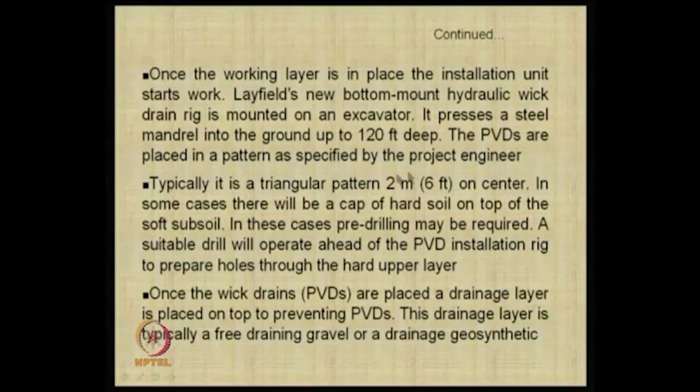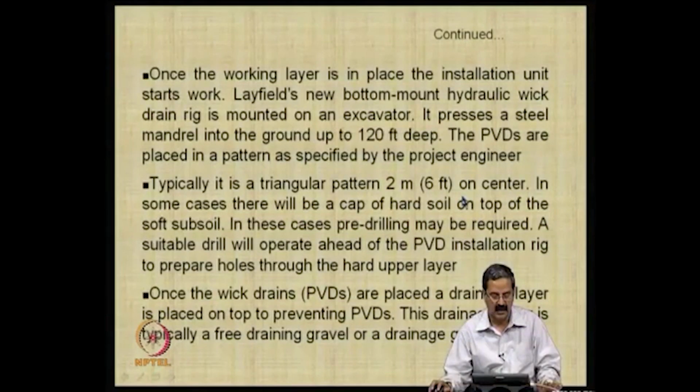Now, you have some of the equipment like the mandrel, we have seen that it can go up to long depths, and it can be a triangular pattern. There are different types of drilling actually, like we will just see, and a suitable rig will operate ahead of the PVD installation to prepare holes through the hard upper layers.